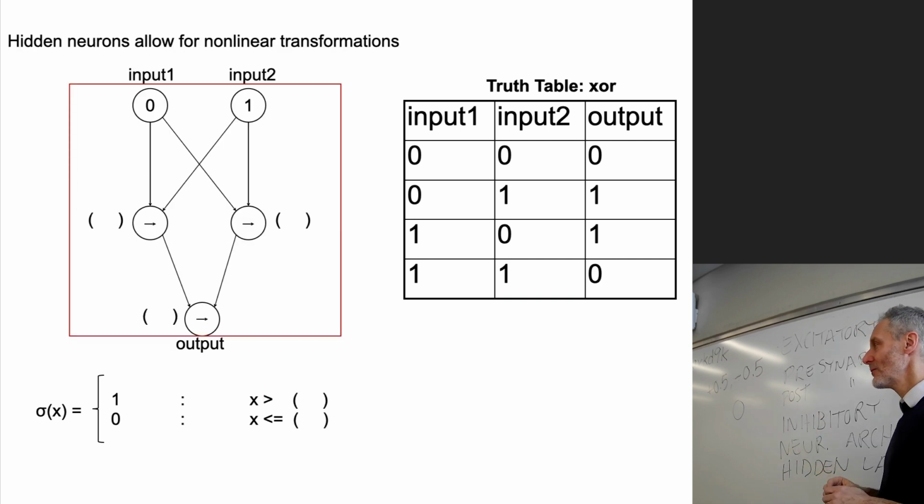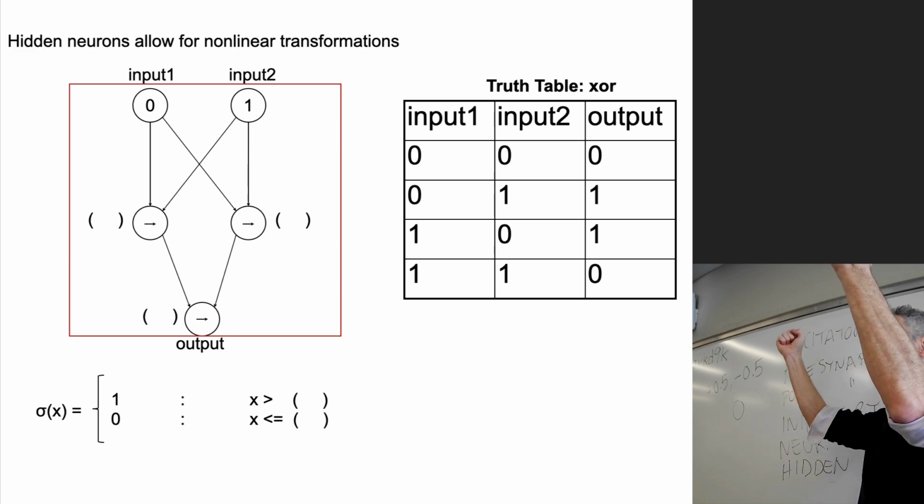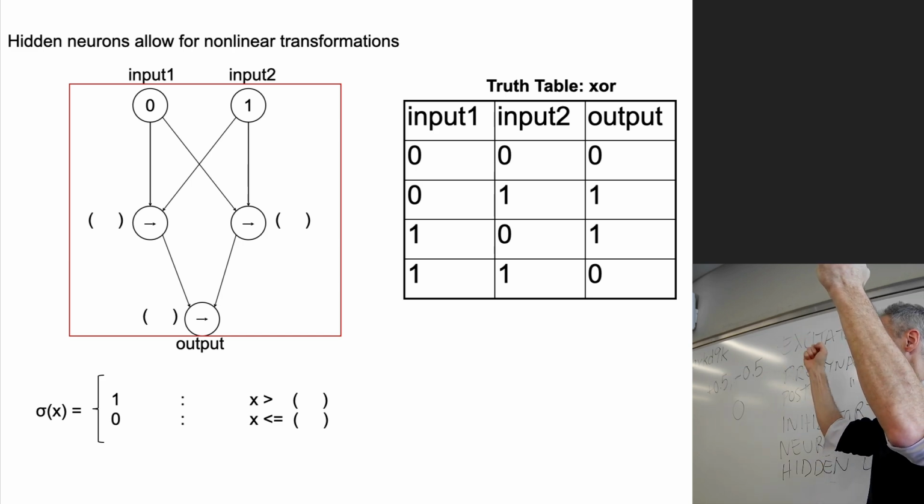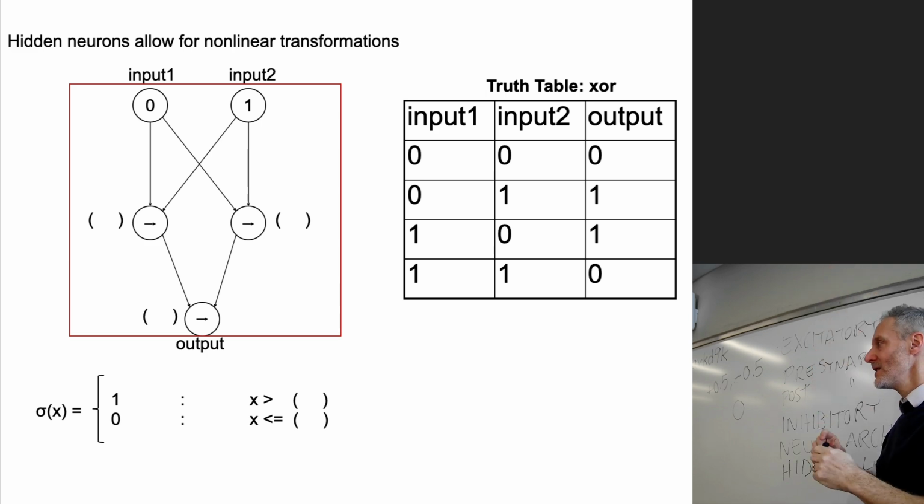Why not AND? We've got one last thing to do. We've computed OR, we've computed AND. We're going to negate AND because... Any ideas? Were you asking me? Yes. Because the two inputs that work for exclusive OR are just like the middle two, and the only one that works for AND is the bottom one. Exactly. So you take that away from regular OR, then you get exclusive OR. Exactly. What you just said, we're going to take it away. We're going to compute AND over here, and AND is going to take away the OR.